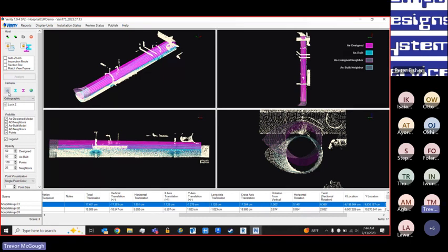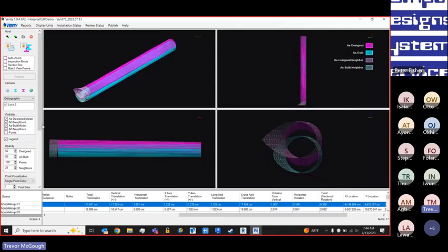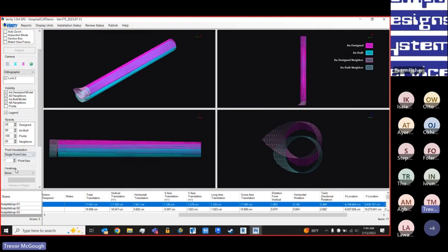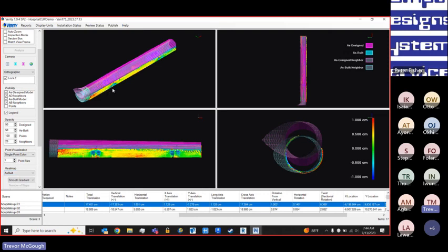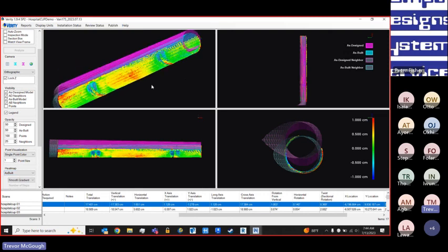On the subject of the point cloud, Verity will also classify the point cloud data around the element, and what it does with that classified data is generate heat maps. Verity will create one of 3 different heat maps. The main one I like to show is the as-built heat map, which shows how the point cloud data fits the as-built or best fit geometry, where green is good, yellow and red are points too far away from the element, and blue are points that are too close.